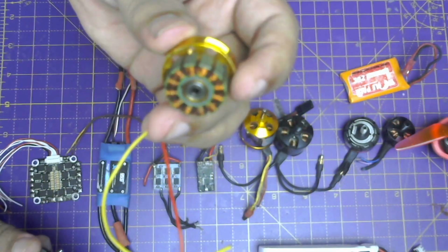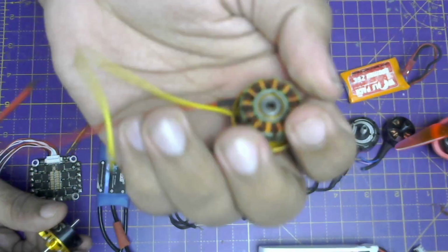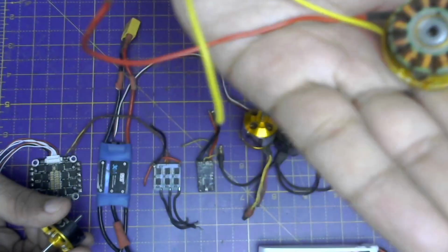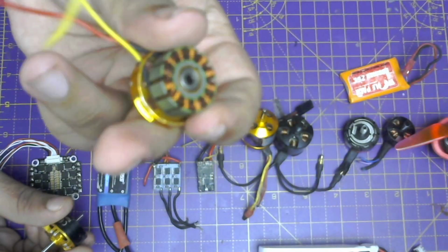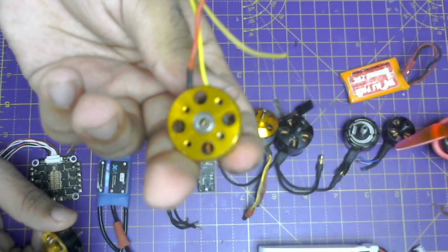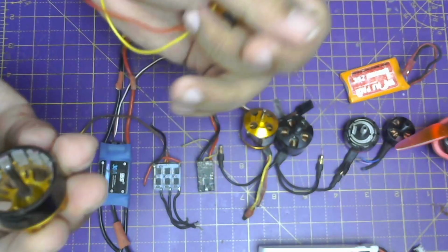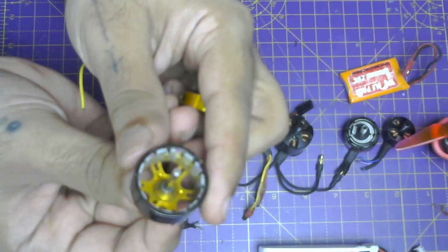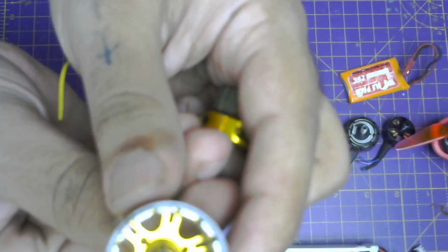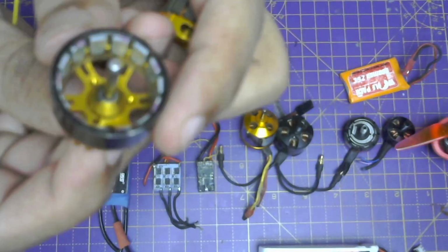So this is the stator of the motor, as I showed in the PPT. This is the same thing happening over here with some copper coils wrapped around. This is a stationary part. You can see the motor bearing here, and this is the part which rotates, it's called the rotor, and it has some magnets on the bell, the permanent magnets.